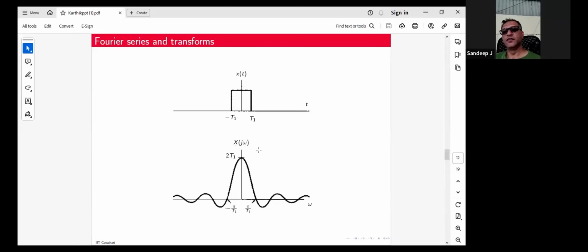I understand that the linear characteristics of the tubes are relatively more linear, the triodes being much more linear, comparably, than the pentodes or whatever. In general, the moment we get into solid state, most of the curves look more like pentode curves, and you do expect some crazy harmonic proportions which are not in your control.